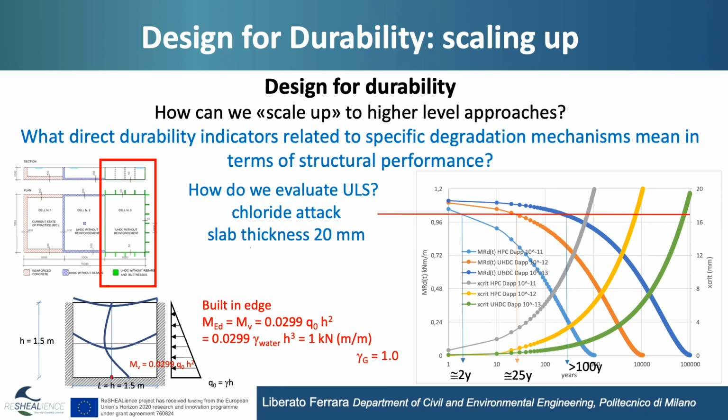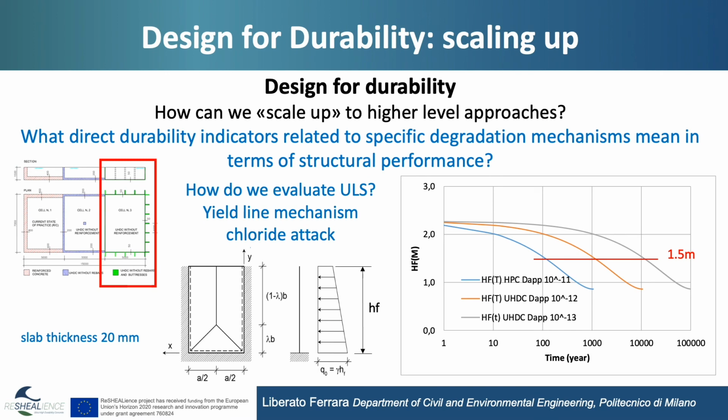And the surcharge case in this instance tells us that if we consider not a cantilever beam-like behavior but a plate-like, slab-like behavior, so we work with yield line mechanism, water surcharge, and so on, we will have an expected service life of 100 years or more. Obviously, this relies upon the redistribution capacity of the structure, which is very important to take into account if we want a more realistic prediction. We also repeated the calculation of the serviceability limit states, and you have the related results in the right-hand graph.